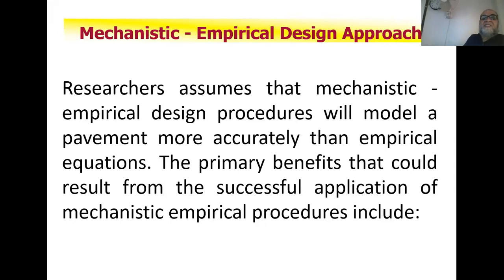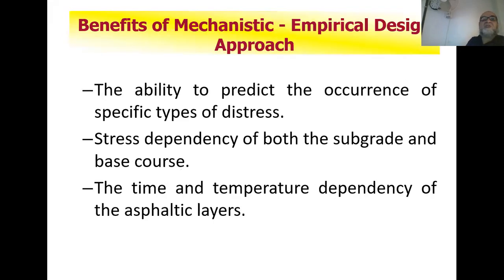Researchers assume that the mechanistic empirical design procedure will model a pavement more accurately than the empirical. The primary benefits that could result from successful application of the mechanistic empirical design procedures include the ability to predict the occurrence of specific types of distresses, stress dependence of the subgrade, and the time and temperature dependence of the asphaltic layers.